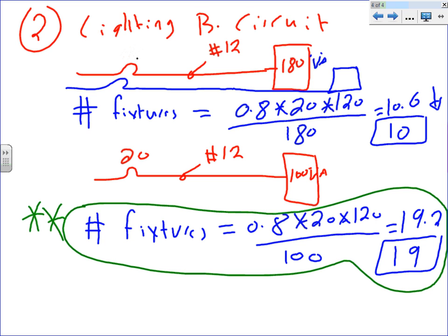So you're going to use the 180 if you have possible future expansion? If you have future expansion, you probably will cut. If I know fixtures, guys, there's not a whole lot of future expansion, really. What are you going to expand on there? You're going to add another fixture. A 19 adding a 20 is not a big deal. That's why I said cut it if you don't go more than 19. Receptacles, I can see how loads change constantly in receptacles. Lights, you put these lights here and they stay forever almost.